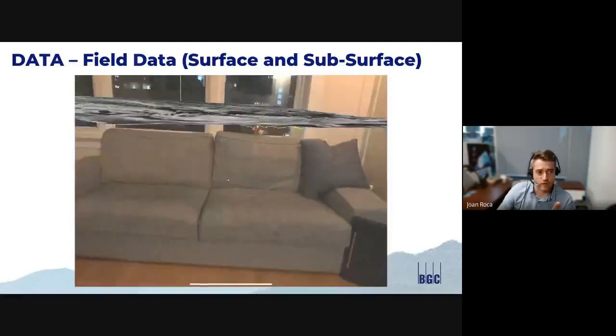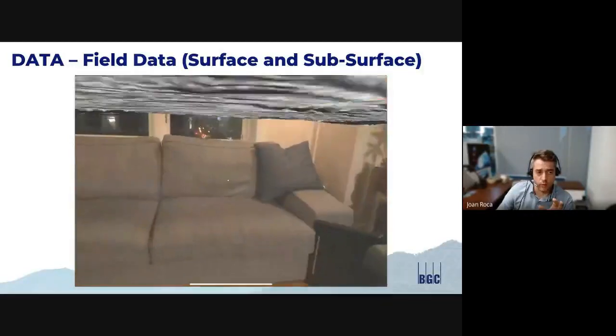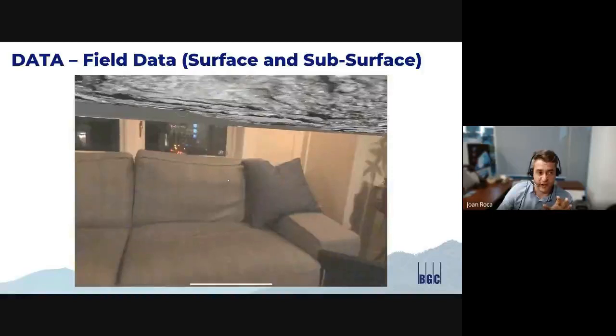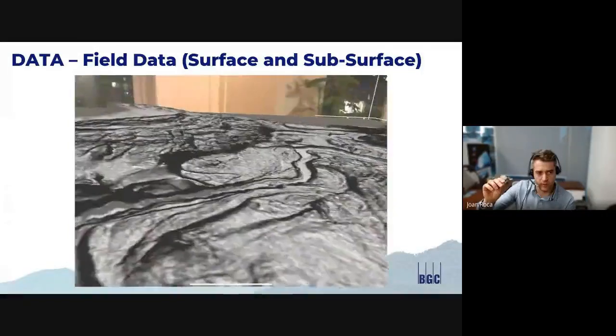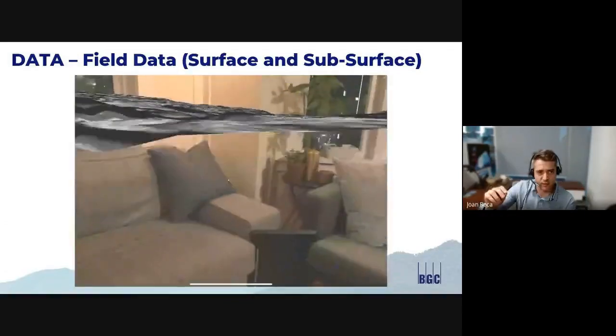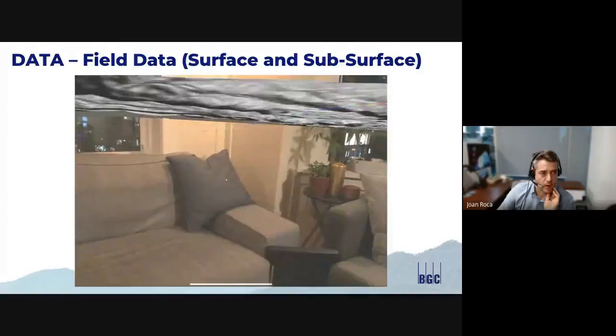And there are some colors. Those colors are showing bending strains. So we use this technology a lot to highlight areas of elevated strain along this pipeline. And then we match it with the LiDAR topography, and then we can see where that landslide is moving and it's impacting that pipe.